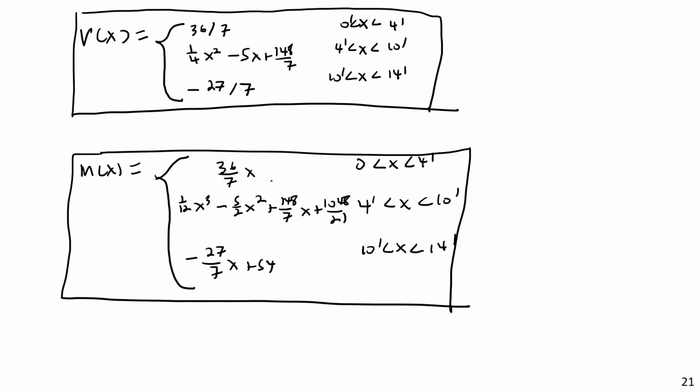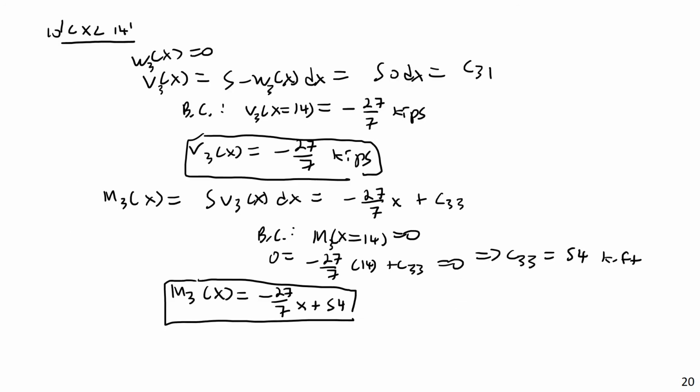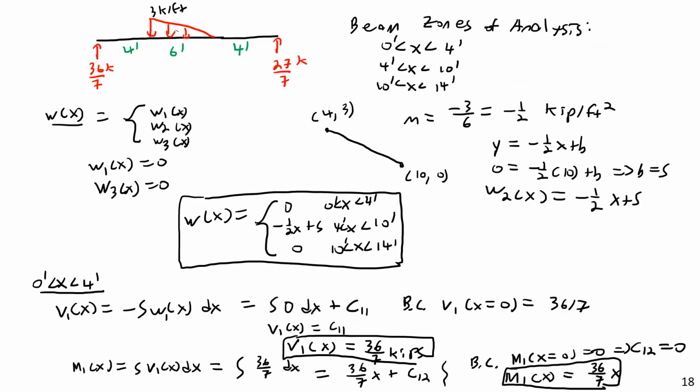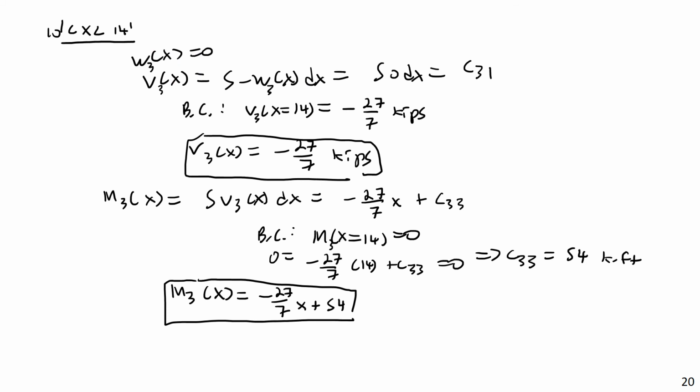Never. So anyway, that is the basic method of applying integration principles or the integral relationships between load, shear, and moment to analyze and get the moment in a shear and bending moment diagram, or get the equations for shear and bending moment in a beam.